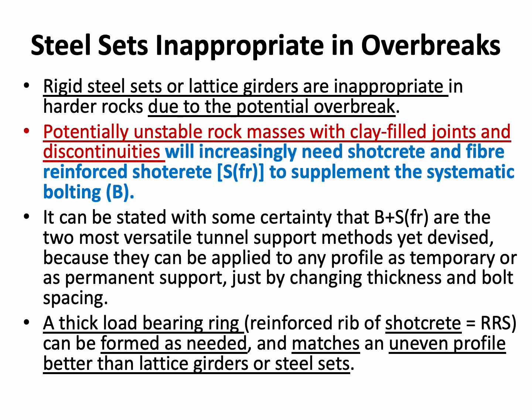Now steel sets are found inappropriate in overbreaks. Rigid steel sets or lattice girders are inappropriate in harder rocks due to the potential overbreak. Potentially unstable rock masses with clay-filled joints and discontinuities will increasingly need shotcrete and fiber-reinforced shotcrete to supplement the systematic bolting.